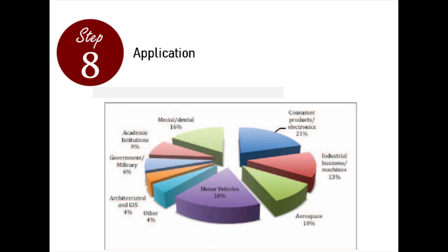In addition, some processes may cause the material to degrade during the build or for materials not to bond, link or crystallize in an optimum way. In almost every case, the properties are anisotropic. This may result in parts that behave differently than if they were made using a more conventional manufacturing approach. However, additive manufacturing materials and processes are improving all the time, and many applications do not require high performance in many of their components. The number of applications for the output from additive manufacturing is therefore constantly increasing.